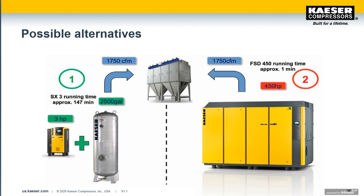With the 3 horsepower compressor, we'd have a pretty high utilization rate. It's going to run fully loaded for almost 2.5 hours to fill that 2,500 gallon tank. On the other hand, we'd have a very low utilization with that 450 horsepower compressor. It's only going to load 1 minute out of every 4 hours. Now, of course, there's probably going to be other demands if you're putting that 450 horsepower compressor in the main compressor room, but if it's just to feed this one big event, it's going to be costly.